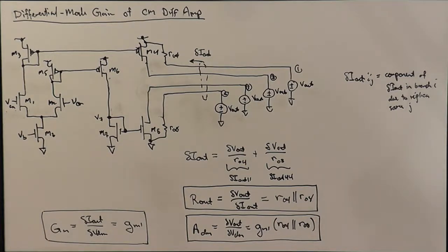That's really nice. It also says that this should have basically the same sort of gain as the simple 5-transistor diff amp does, for a given bias level and a given transistor length and early voltage parameter, they should have comparable gains.